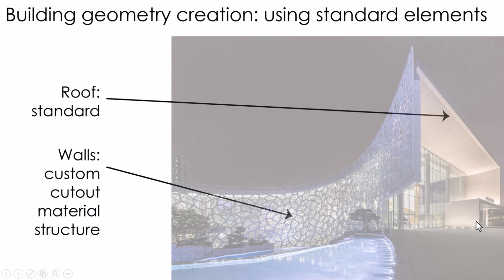You could do that as just a mass in place, and draw it as an extrusion, draw the shape and then create a form from it. Or draw an arc and create a swept blend. This front piece, you actually probably could do the cutout pattern based on this. I believe it's what they call a Voronoi pattern. And I'm sure if you went to the architect's website, you would find that pattern somewhere and apply that pattern as a cutout to a simple curving wall, and you're done. That's it. There's no windows, there's no glass, there's no nothing in there.